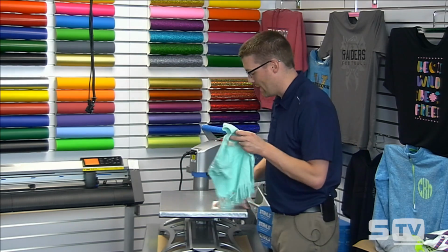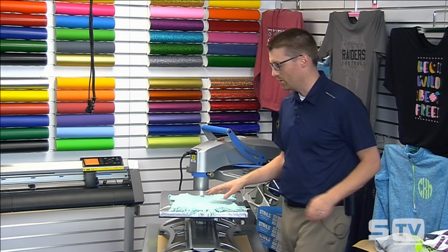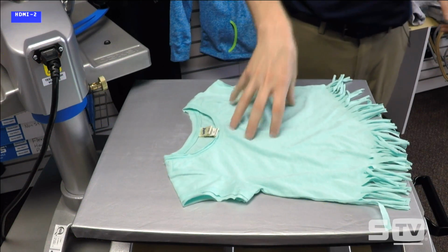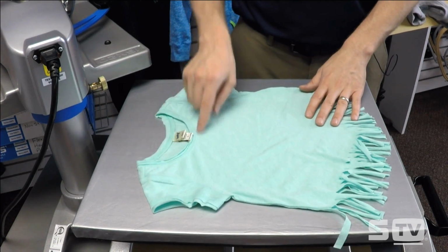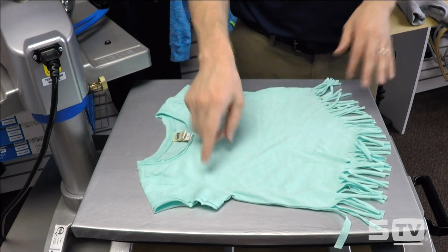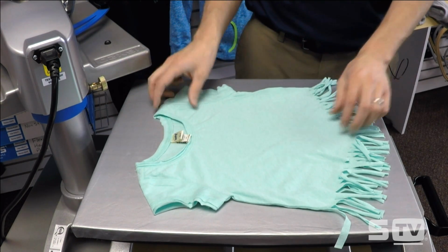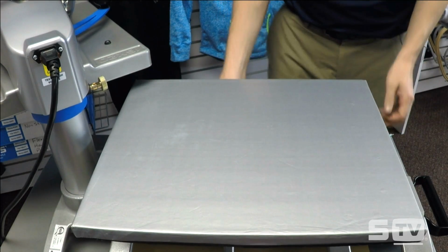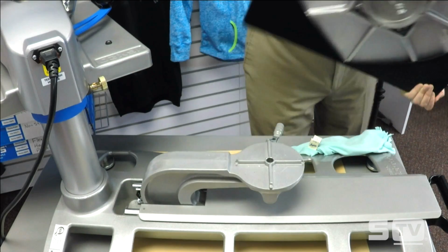So I'm going to have to swap out the attachment on my heat press to do this one. If we take a close look at the heat press, you could lay this flat perhaps and get away with it because the seams are over here, but you run some risk of glossing the garment up in those areas since this is a size 4 garment. So what I really want to do ideally is swap out my attachment, just a quick clip and go.